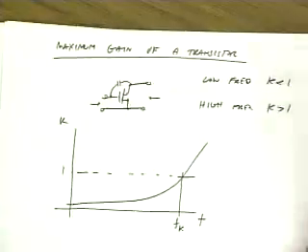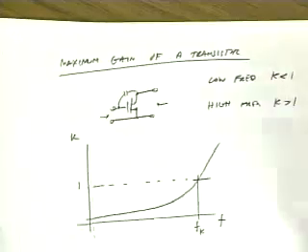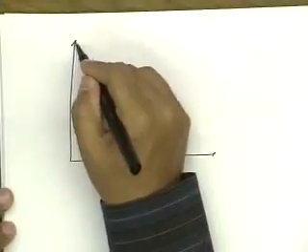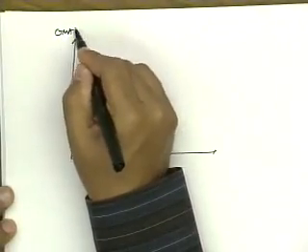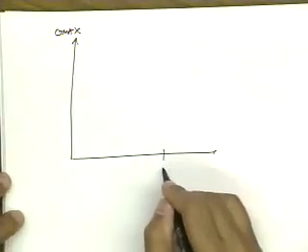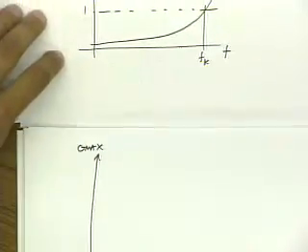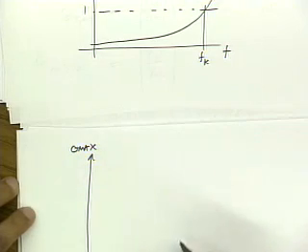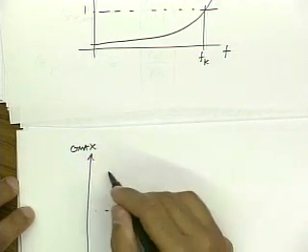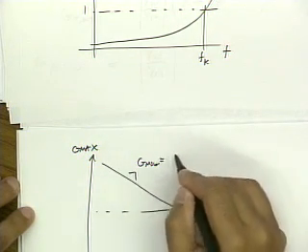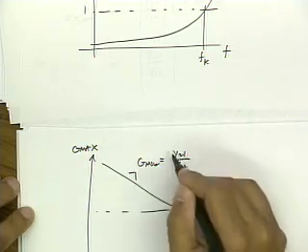So now if I plot the maximum gain, the maximum stable gain I can get from my device, so let's just call this G max, then up to the knee frequency, it's unstable, so I have to use the expression GMSG, which is just simply y21 over y12.